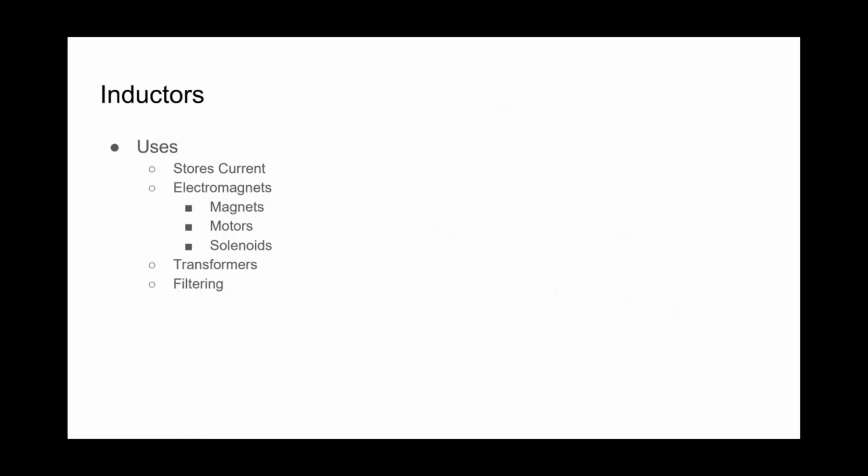All right. You can use them for filtering. I'm not going to go into it. However, it is a more powerful filter. So with RC filters, they're called, you kind of get this slower roll-off because they're a single pole. And you can learn more about that later. But these are what's called a secondary pole. So probably not that sharp, but they're still much sharper. So this is because it has two poles. Again, go ask your professors if you want more information, or you can ask Joe or I.